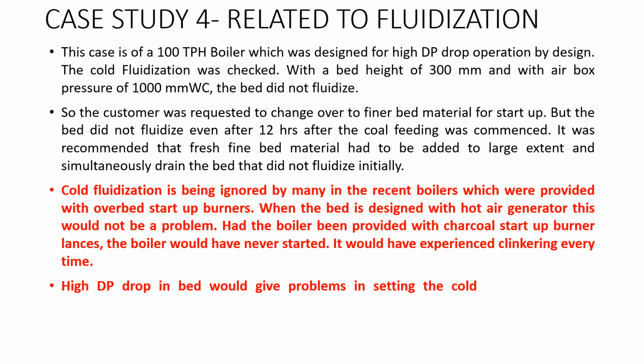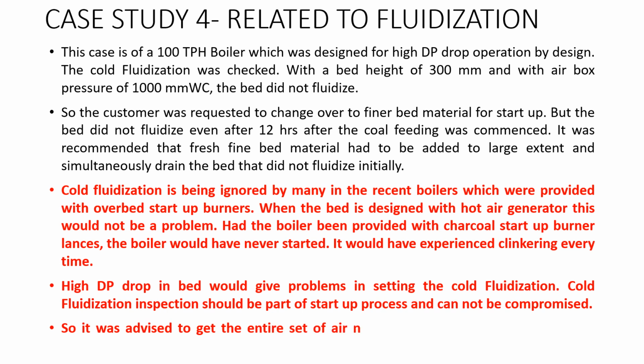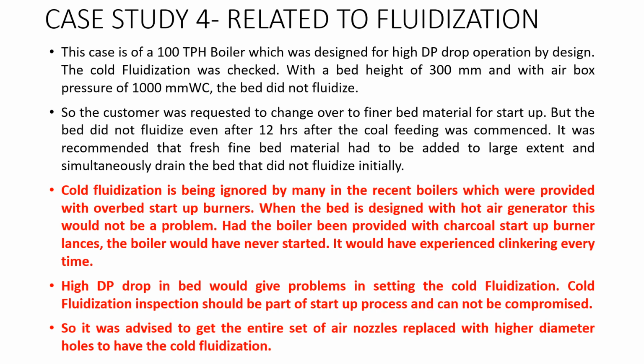So a high DP drop in the bed would give problems in getting the cold fluidization. Cold fluidization inspection should be a part of the startup process and cannot be compromised. So it was advised to get the entire set of air nozzles replaced with higher diameter holes to have the cold fluidization. So the main focus should be on the fluidization.